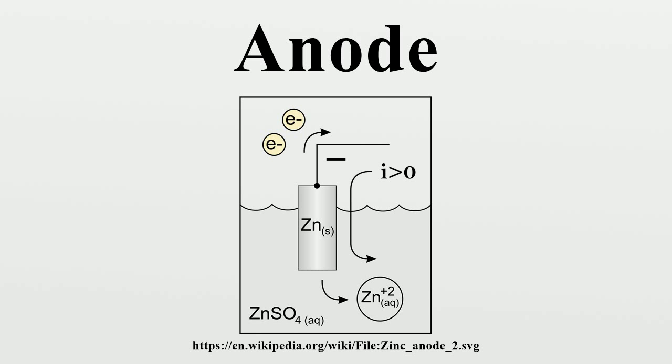Sacrificial anode. In cathodic protection, a metal anode that is more reactive to the corrosive environment of the system to be protected is electrically linked to the protected system, and partially corrodes or dissolves, which protects the metal of the system it is connected to. As an example, an iron or steel ship's hull may be protected by a zinc sacrificial anode, which will dissolve into the seawater and prevent the hull from being corroded.